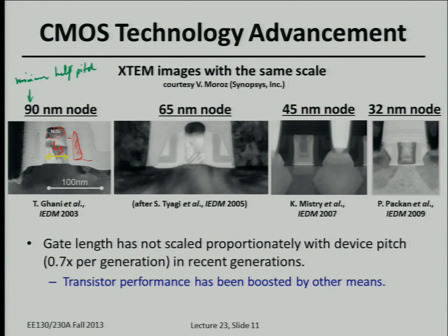And the top of the gate is silicided. The polysilicon gate is silicided, just like the source and drain regions in the contact areas. So silicide is here and there. Basically, the deposited metal is heated up and reacts with the silicon. Since the gate is silicon and the source drain regions are silicon, they form silicides there to reduce series resistance.